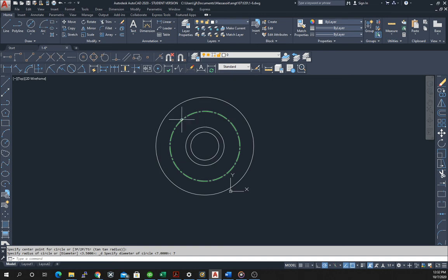If you don't do this, when you dimension it, you would have to give them x and y coordinates. This way you can say they're on this bolt circle that is centered in the center, and they're located, in this case, if the diameter is 5, 2.5 inches out from the center.